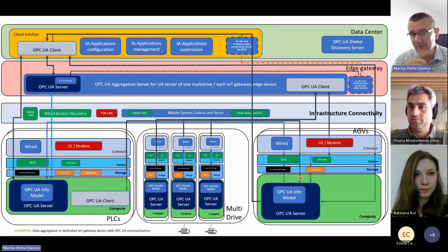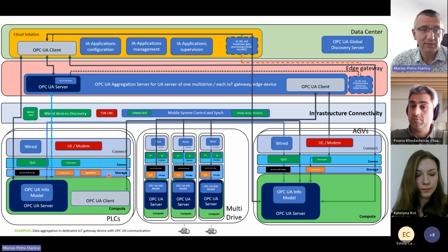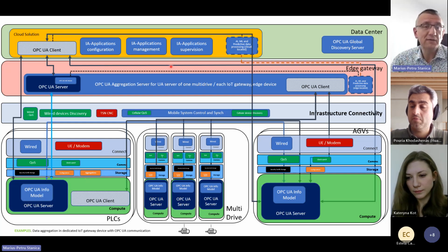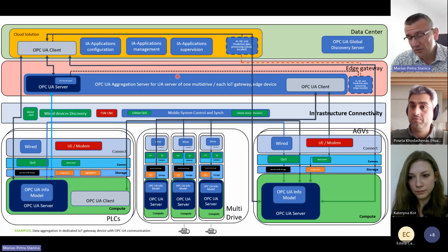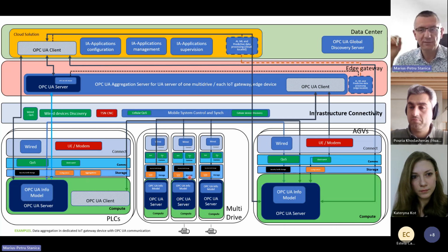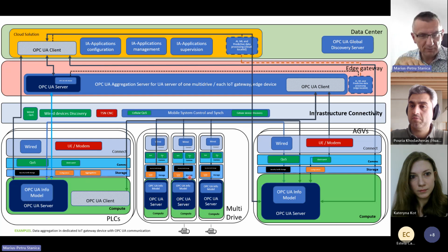Those other elements go to the second part of your question: where do you handle that? You handle it at the level of the drive, at the level of the PLC, or, let's say, in the edge. In general, in the edge, you don't handle that kind of information for swaying, anti-swaying, as it's called for cranes and so on. You handle it at the drive level or at the PLC level.